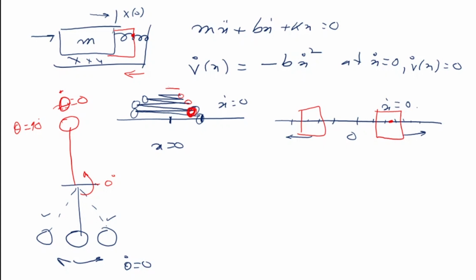At the end points here, there is an acceleration which is pulling the mass backwards. And at this position, there will be an acceleration in that direction. Because of which, although x dot becomes 0, the mass is subjected to an acceleration which is going to pull it back again. So it is not a stable point. The mass cannot go and sit there. It will immediately go in the reverse direction. And the only stable point is here at the equilibrium point.